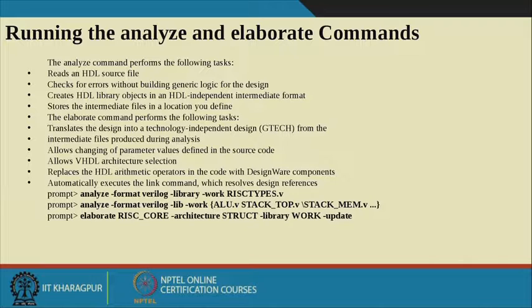Now I want to analyze multiple Verilog files simultaneously. Within this parenthesis, if you just name all the Verilog files, all of these files will be analyzed simultaneously, one by one. After analyzing, I have to elaborate.